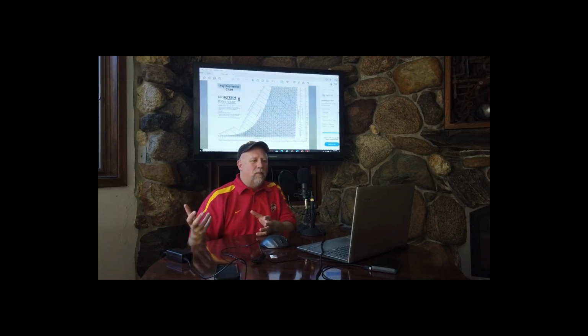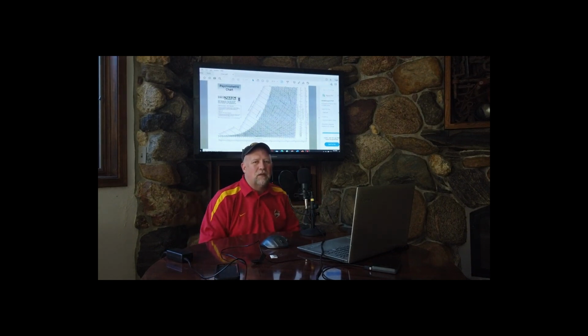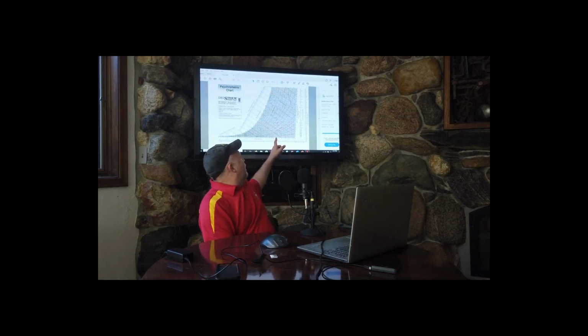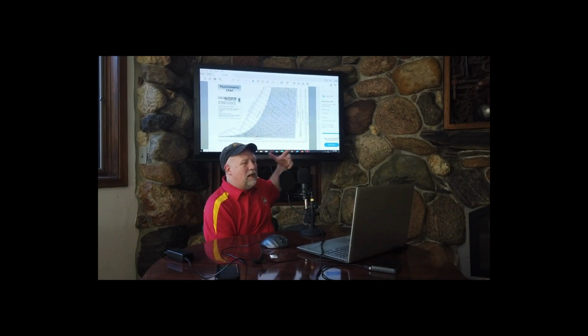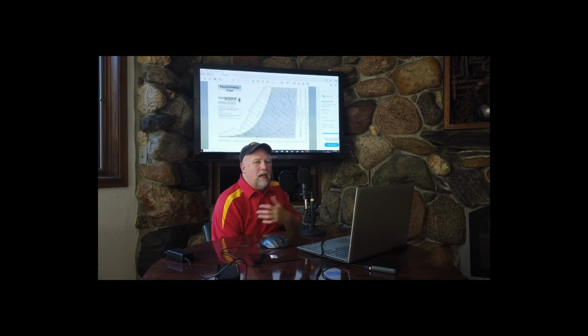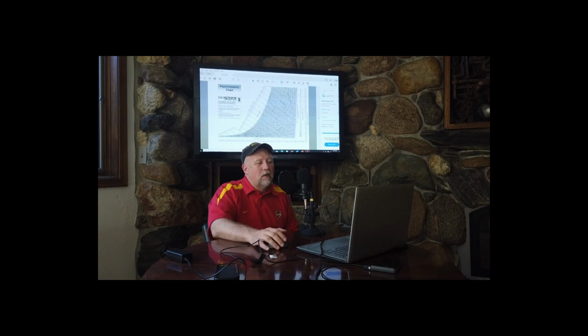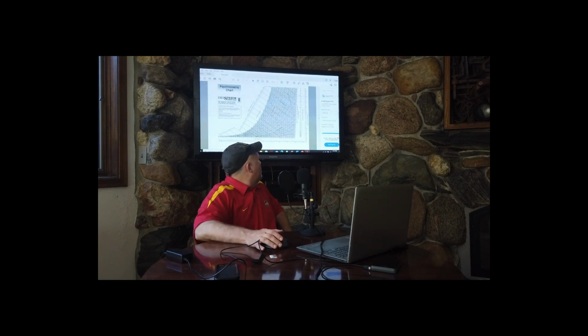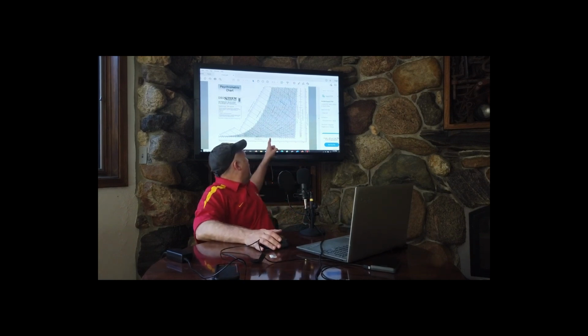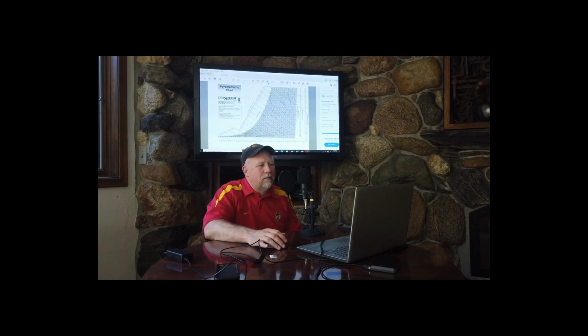So if I walk outside, I've got a thermometer and a wet bulb temperature sensor, I can get those two values. I could also find what the relative humidity is outside. If we just check the weather conditions outside, we can get dry bulb temperature, and maybe a humidity. And then I could look up all the other values. What I want you to do is just do that. If we look at 95 degrees Fahrenheit, 78 degrees wet bulb, go ahead and plot that.